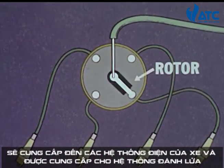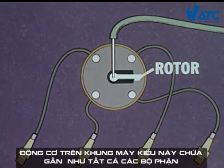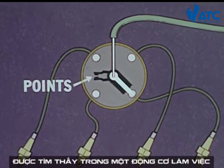Inside the distributor is a rotor, which as it turns touches a series of contacts, one of which is wired to each spark plug. The points open and close as the rotor turns, interrupting the current to produce the fuel-igniting spark.